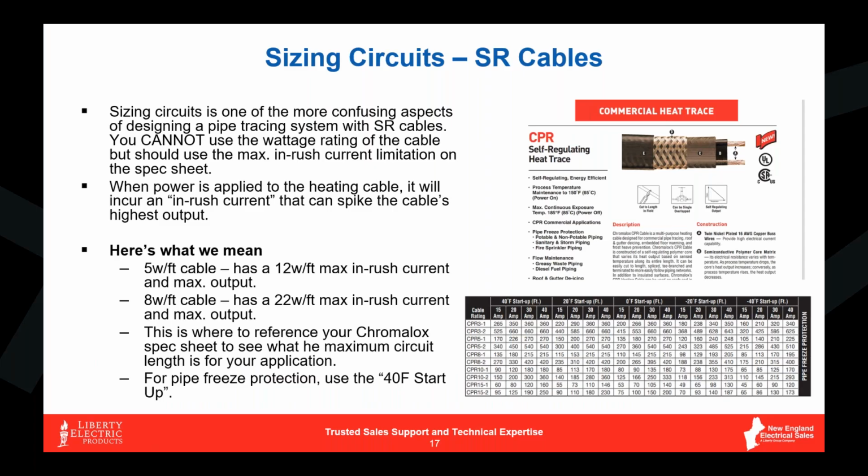So take a look at 8 watt a foot cable. Whereas we used that example earlier in this presentation, a 5 watt a foot cable draws a maximum of 12 watts a foot. Well, an 8 can draw a maximum of up to 22. So that really changes things as far as how many circuits we have to commit to using an 8 watt a foot cable to make sure we can get it all on there without your end user suffering nuisance trips from GFI pops and loading up these breakers a little bit too much.